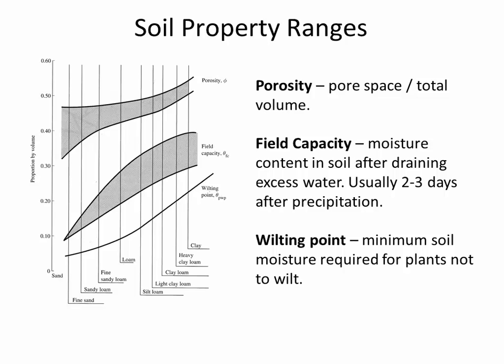Clay has to be more wet or else the plants will begin to die, is the interpretation of this line going up. The reason why the wilting point is higher for clay is that the clay is holding on to the water. The clay won't allow the plant roots to withdraw the water as easily as silts and sands. In the case of sands, the plants can continue to withdraw the water even when the moisture content's very low.